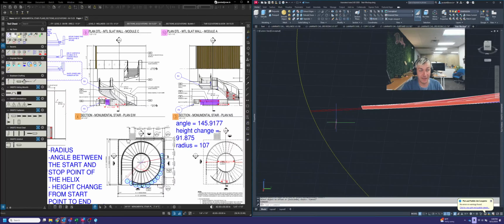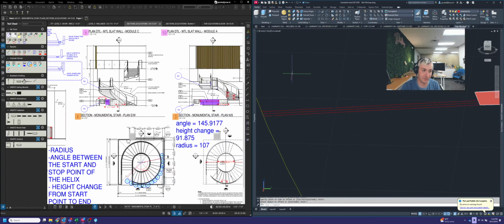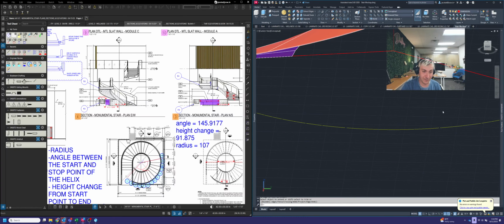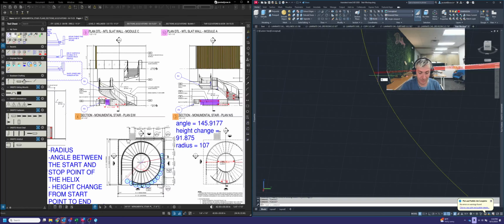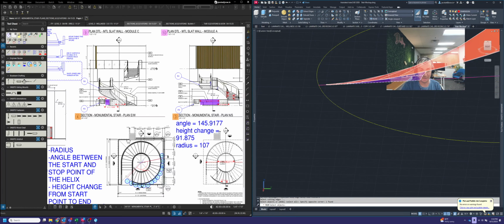Because if we're assuming that the reveal is a 1/4 inch, we also need to offset a center point. We're going to go 0.125 this way and 0.125 that way, which will end up being the start and stop point of our array path that we use to draw the different reveal spaces there. So it ends up being just like you would do for a panel set, just a little different because you're dealing with something on a weird curve, but you're treating it the same way because really it's not too different than what we're used to seeing.